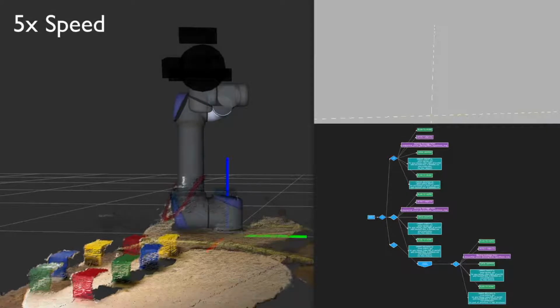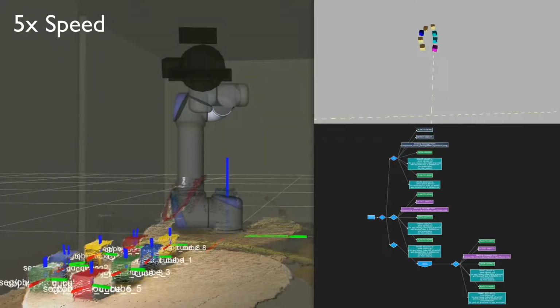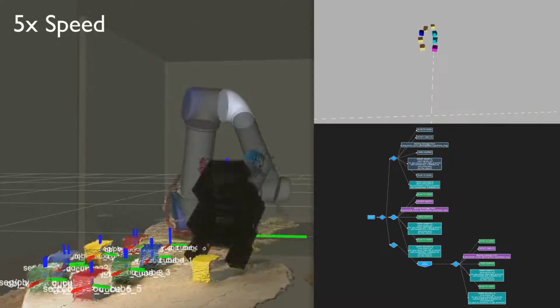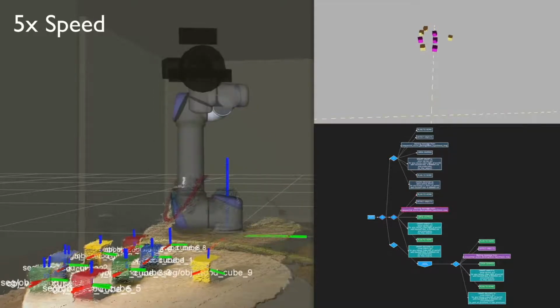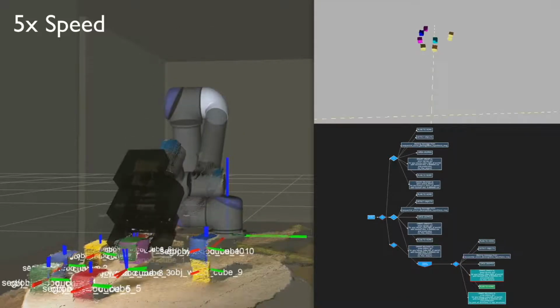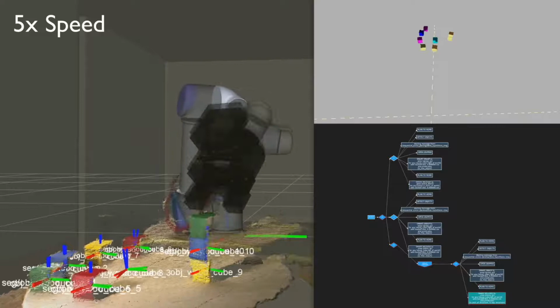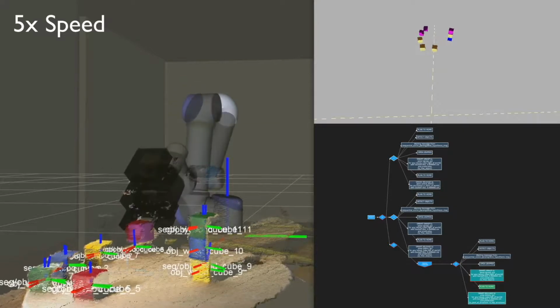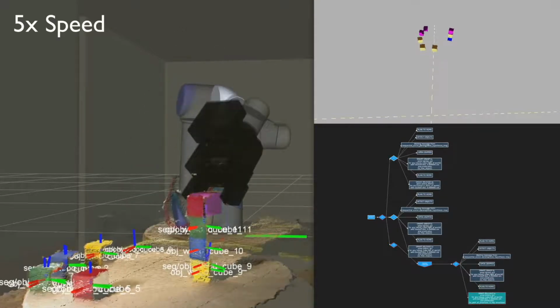This following video shows the sequential scene parsing algorithm used in the block stacking task. In this task, the scene parsing will provide both physically consistent object poses and the current structure of the scene. Based on the detected structure, the robot will grasp the free block and put it on the top of the stack. To speed up the best scene estimation in this test, the scene parsing will only consider the best pose hypothesis from the pose estimator that corresponds to the maximum data consistency.